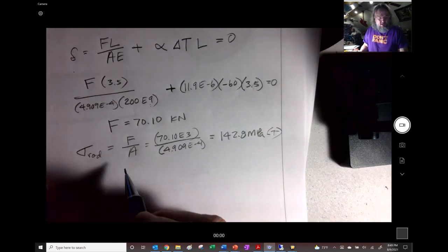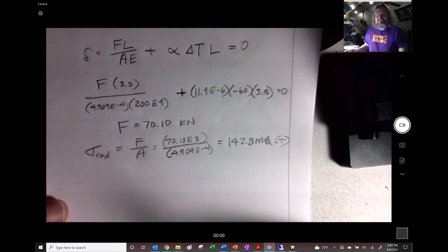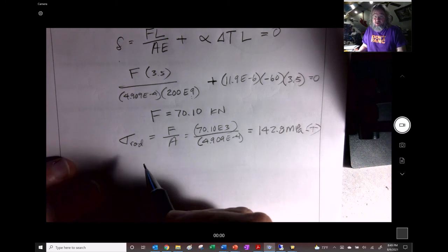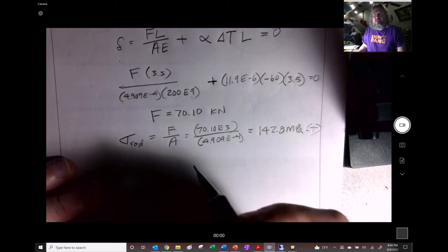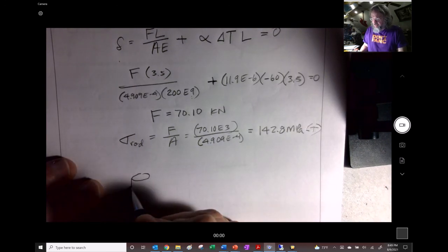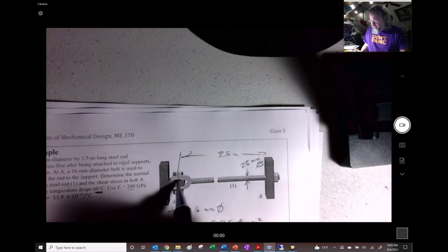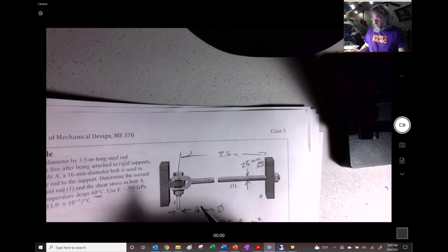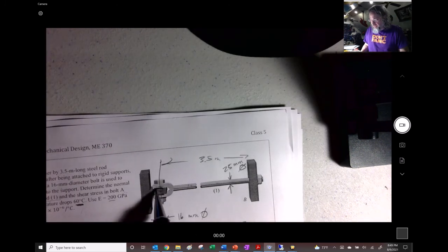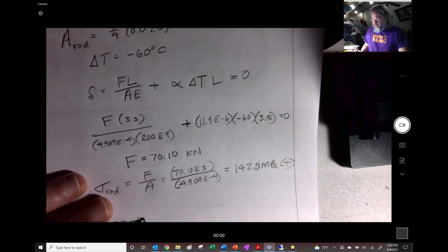Yes. The shear of the bolt, right? So this is actually direct shear. I might have said in a previous class that we wouldn't be doing any direct shear. But next semester in ME370, we do a lot more of this right here. If you were to take a look at a free body diagram of the bolt, like right here, you'll see that it has these two interfaces right there. So if we just cut the bolt off right here and right there, we would see that here's this part acting onto it, and then here's the other part acting onto here.